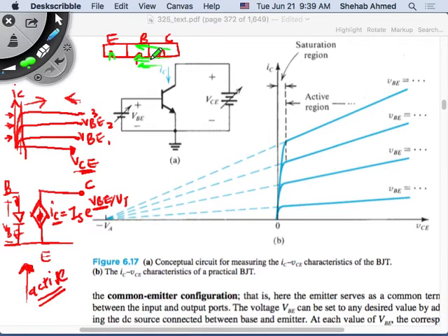So is it a significant effect? No, of course here it's amplified, right? So ideally, we'll consider it a straight line. But if it's going to find more charges to move over, it will increase the current with VCE, right? So before it was not. Before, VCE changes were not affecting my model at all.